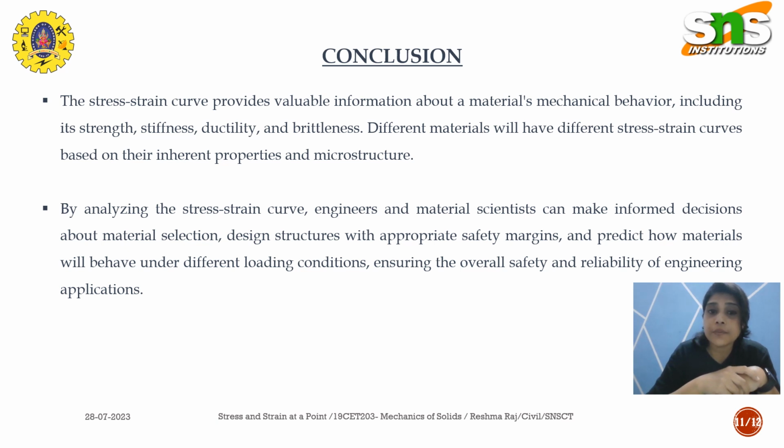The stress strain curve provides valuable information about the mechanical behavior of the material. It includes the strength of the material; we can know the ultimate strength. We also get the stiffness, ductility, and brittleness of the material, all from this curve.